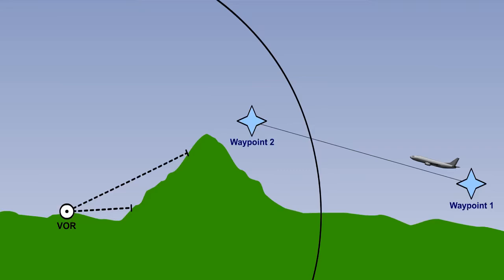Let's look at some limitations associated with a simple 2D system. Because VOR-DME emissions are line of sight, a pilot must be aware of the altitude at which he chooses to fly and must consider the masking effects of any intervening features, such as mountains. VOR beacons have a designated operational coverage, so the waypoints chosen must be within the DOC.